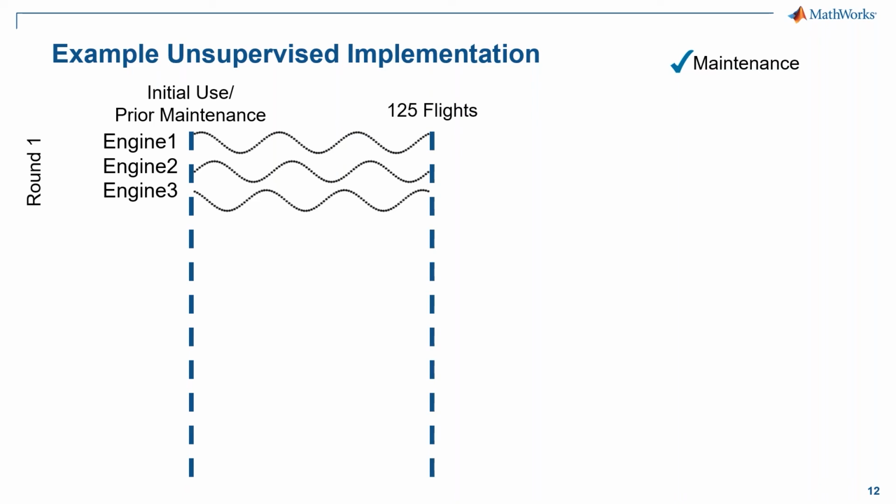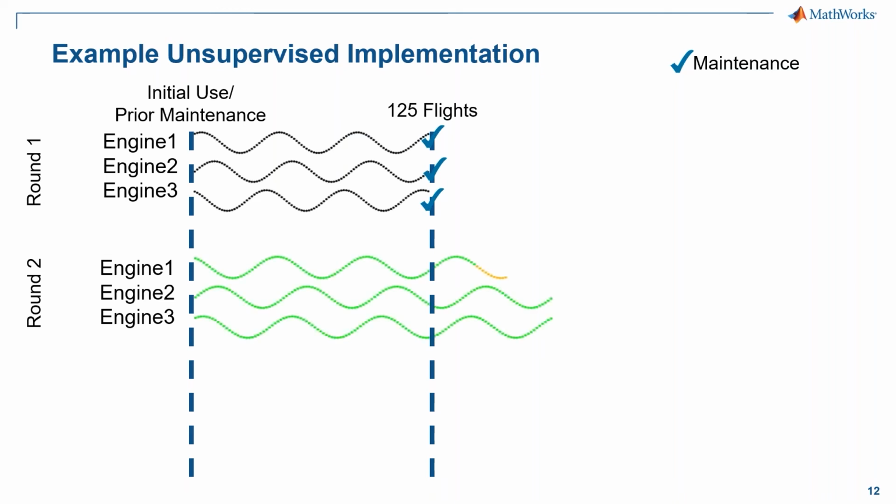But now that we have a condition monitoring system, whether it be the unsupervised one we have now, or that classification one I mentioned, instead, what we can do is say, okay, we have this in place. Let's start testing it. We are at 125 flights. Let's push it out to say 135 flights, and if it spends 3 flights in a row in yellow, then we'll bring it down for maintenance early. Otherwise, we'll bring it down at 135.